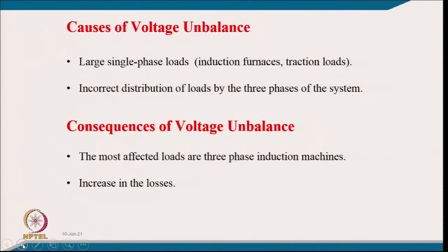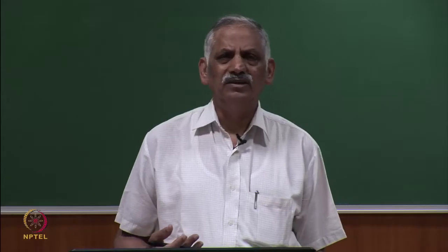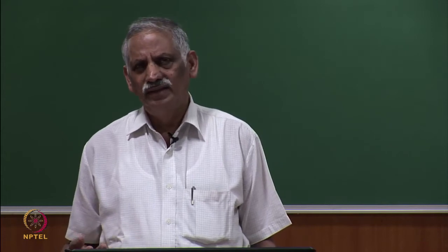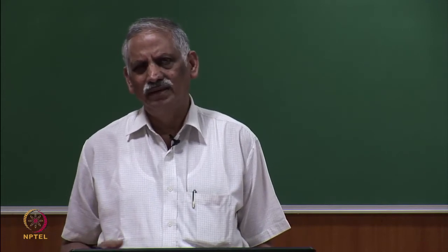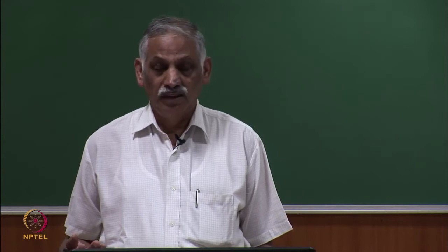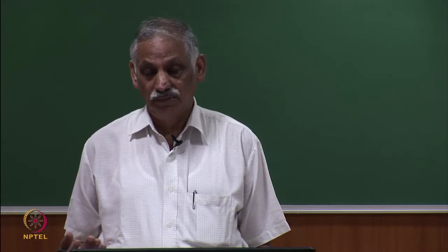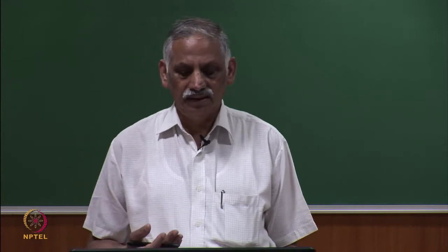Large single phase loads, like induction furnaces, which are of quite large rating, maybe up to 500 kilowatt. The induction furnace is virtually a single phase load. We try to balance it out, I hope you remember, normally using the Scott connection, and you get 2 isolated single phase supplies and can connect 2 different furnaces. If both furnaces draw equal load, it gets reflected like a balanced load. You are virtually converting 3 phase to two phase, but the two phases are isolated, so you can feed two separate furnaces. But you can't guarantee that both furnace loads will be equal all the time, so that certainly gets reflected as unbalanced current.